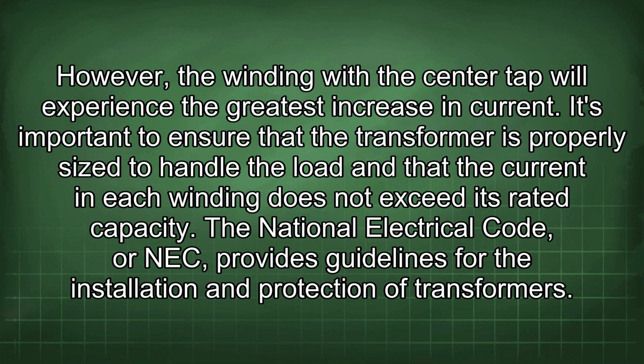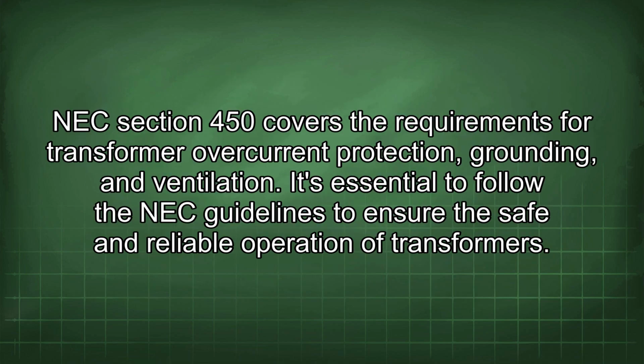The National Electrical Code, or NEC, provides guidelines for the installation and protection of transformers. NEC Section 450 covers the requirements for transformer overcurrent protection, grounding, and ventilation. It's essential to follow the NEC guidelines to ensure the safe and reliable operation of transformers.